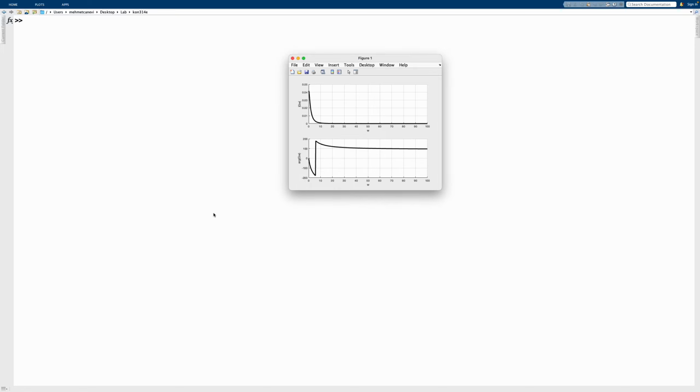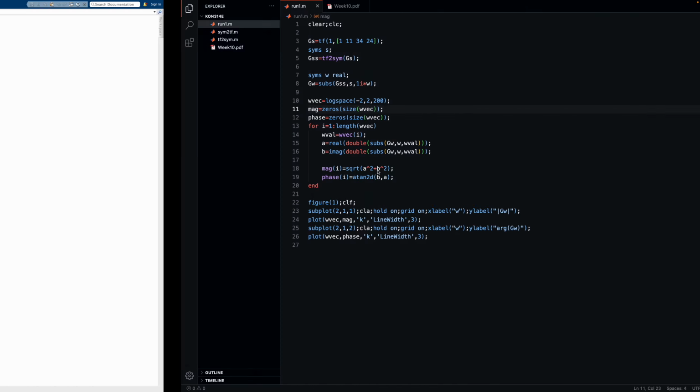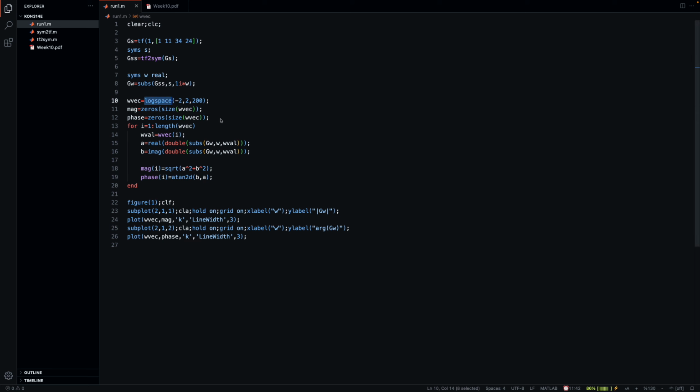But of course, still we're not satisfied with this, because the x-axis, which is the frequency itself, is spaced linearly on our plot. And that's not what we did. We basically chose it to be logarithmic. In order to be able to fix this, we need to basically have a little hack here, which basically takes the get current axis handle and accesses its x scaling and then converts it into log, which is linear by default.